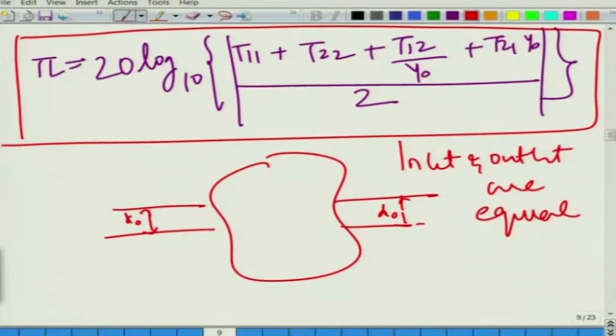So, once we have this condition, then of course, your things would simplify a bit, and probably as we go deeper into the analysis of such expressions, we can actually show that transmission loss and insertion loss are equal in the limiting case of the radiation impedance.